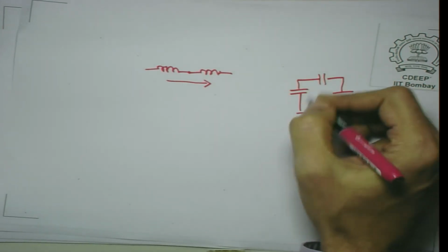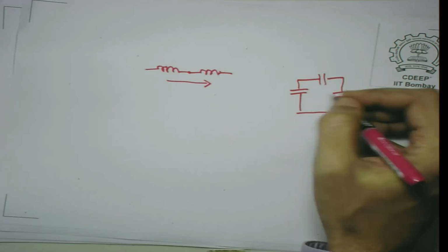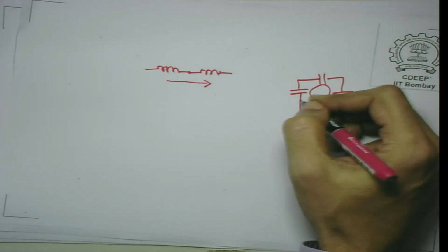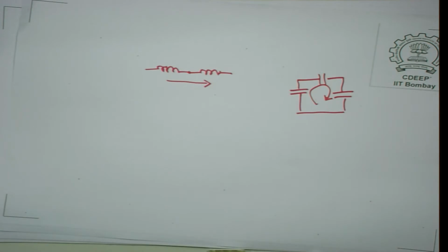The voltages on all these capacitors cannot be specified independently, because if you apply KVL, there is a constraint that the sum of the voltage drops should be equal to 0. So, it is not true that for all capacitors and inductors in a circuit, the initial conditions can be given independently, at least in ideal circuits.